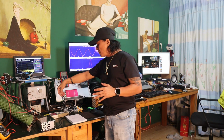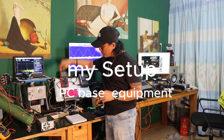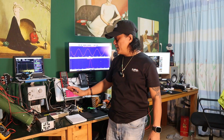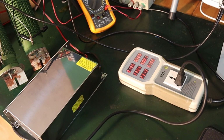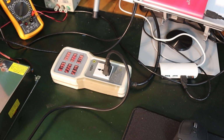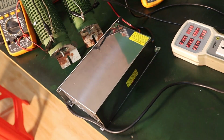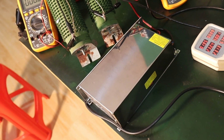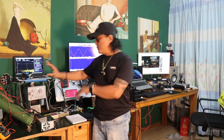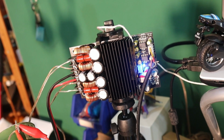Let me start with the high power from the 220 volt AC household. We got the power meter in here. This is where I plug in the 220 volts for the SMPS power supply. The SMPS power supply is 48 volt 800 watt, and the voltage goes down to 48 volt DC, and that is the input power to the Class D power amplifier. Currently right now it's the module B TPA3255 chipset, and the speaker output, the left and the right channel, goes into the resistive load.